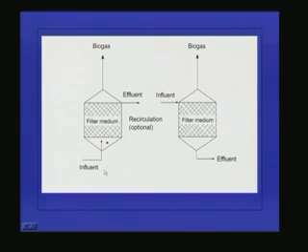And the reason for the clogging is that the influent will have a lot of suspended solids. So those suspended solids will come and sit here in the bottom portion of the filter. So that can also clog the filter. So what will happen afterwards? There may not be sufficient flow and a lot of head loss will be there, etc. And sometimes, if the influent flow rate is not sufficient, what is usually done is to recirculate a portion of the treated effluent here, so that it will get enough velocity for the flow. So this is the anaerobic filter.